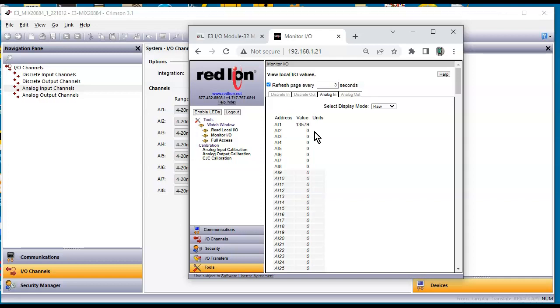So we're going down. We're 8, 7, 6, 5. All right, so here we are. Here's 4.1 milliamps. There's that same 176 again. Here's 4 milliamps. So it's going to say, oh, look at that, team. So it goes to negative 17 between 4.0 and here's 4.1.